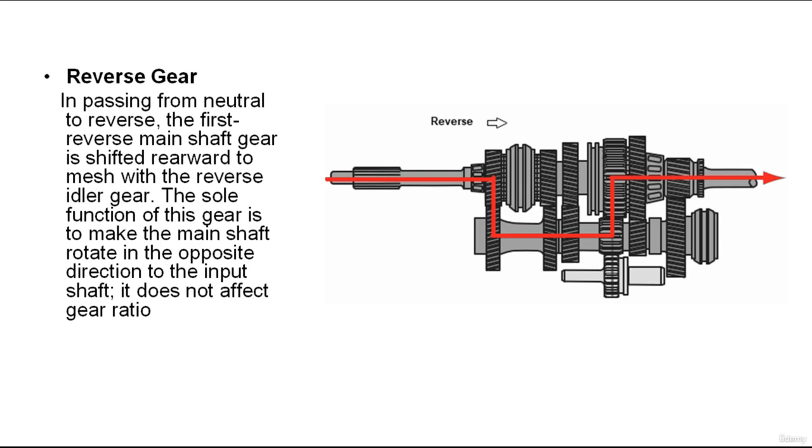The idler assembly is made of a short drive shaft independently mounted in the transmission case parallel to the counter shaft. The idler gear may be mounted near the midpoint of the shaft. The reverse speed gear is actually the external tooth sleeves of the first-second synchronizer. When reverse gear is selected, both synchronizers are disengaged and in the neutral position in the transmission. The shifting linkage moves the reverse idler gear into mesh with the first-second synchronizer sleeve.